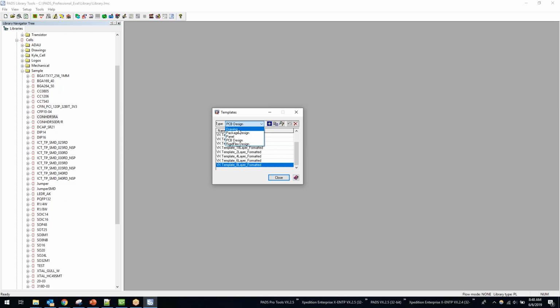The other things in here include a drawing template for the drawing editor, package design if we're utilizing a bare die or chip on board type of design, panel design if we are going to be panelizing it within FabLink, PCB design within Pads Pro layout, as well as a rigid flex design. Okay, so these are just our different partitions here, and I can have different layout templates depending on which pull down I have. We're just going to be working with PCB design today.